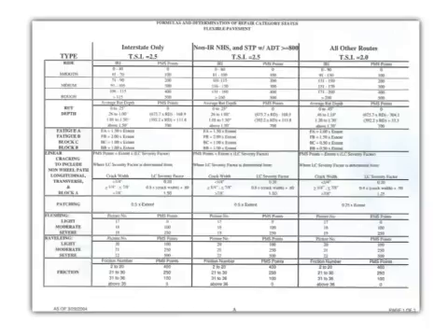This is another example of how we measure the stresses, and eventually how they come up with one simple index to measure the pavement performance. For example, as you can see here, we have IRI measurements to measure the smoothness of the road, and also we have rutting, fatigue cracking, patching, friction, and then we define a certain extent, and once we define the extent, we also define PMS points.